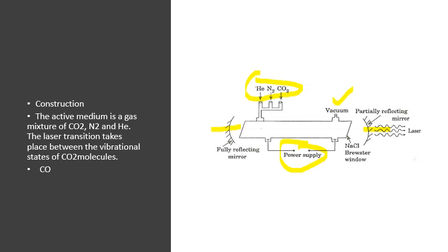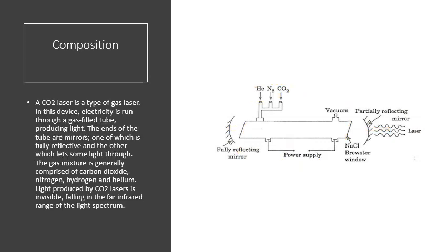On both sides we have used NaCl Brewster windows. As we have discussed, in the CO2 laser we use a gas-filled tube. At the ends we have mirrors, one fully polished and one partially polished, and the gas mixture is filled here.